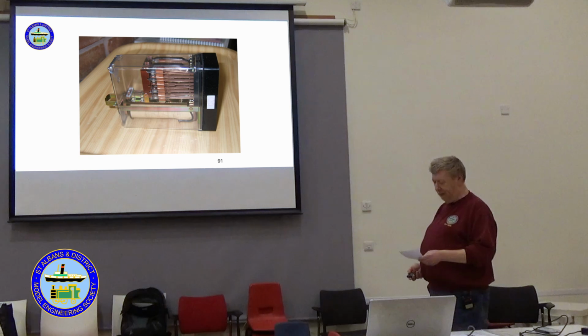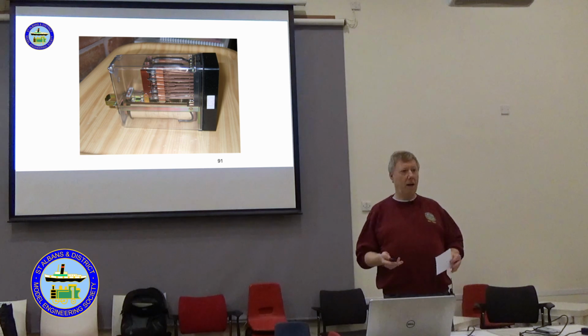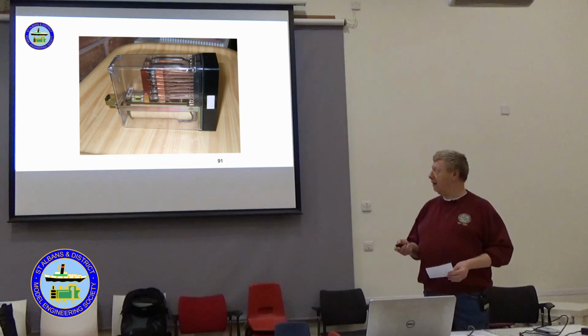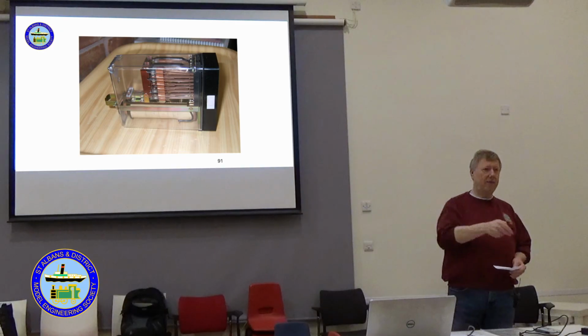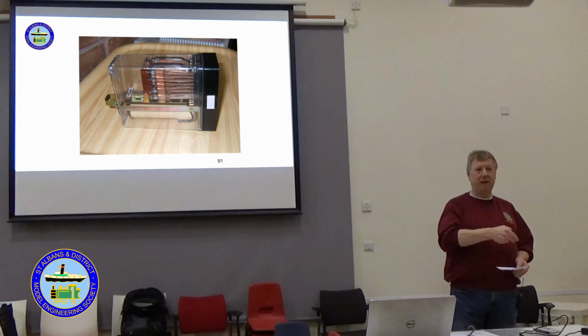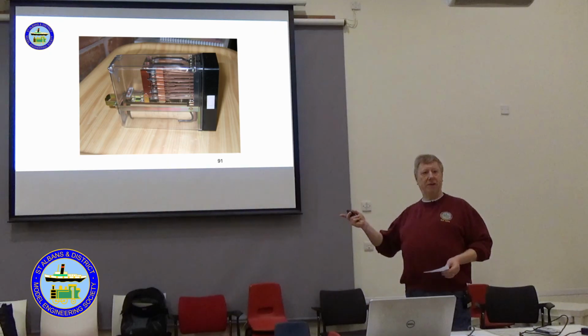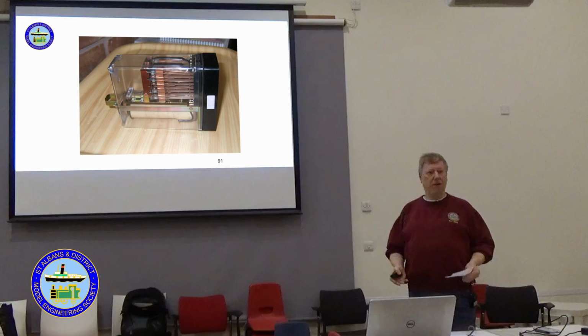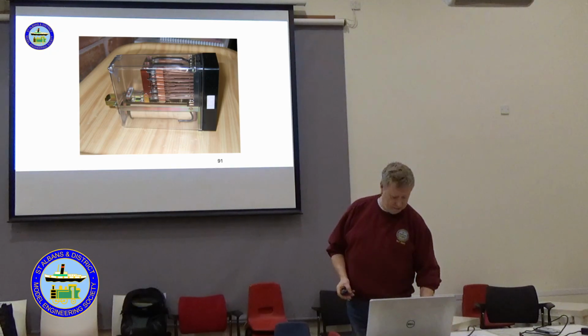These are the other way. And they use things called relays. Basic old technology. Basically, you have a current that goes up one wire, through the relay, keeping it energised, down the other wire, down the other rail. As a train comes along, it short-circuits that, de-energises the relay, which activates all the stuff. Triggering all the warning devices and signals.